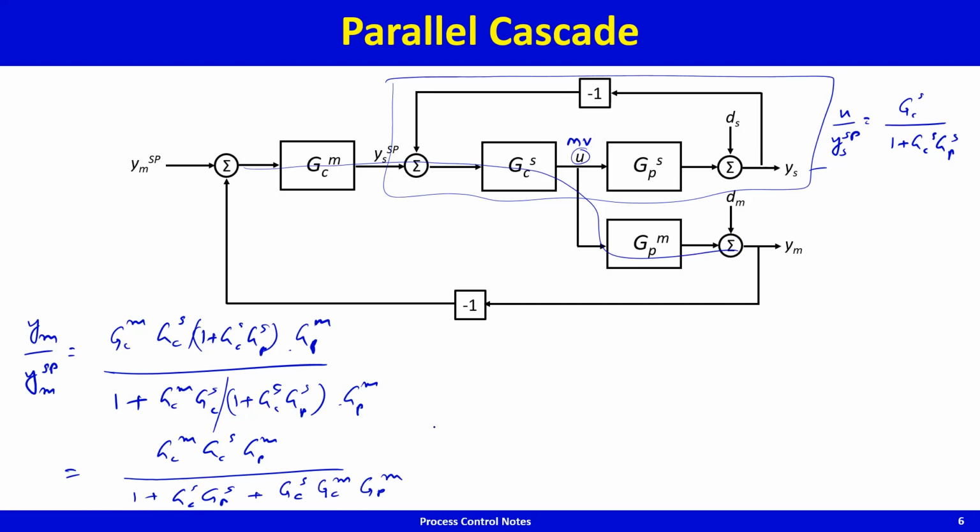So if I want the transfer function with respect to d sub s, what would that be? How would you do that from first principles, or using block diagram algebra? Okay, let's look at this point, or let's look at u. So there is a u change because of disturbance.